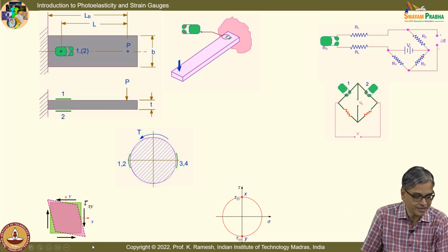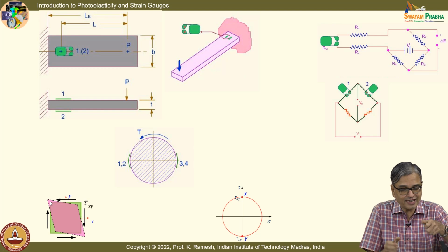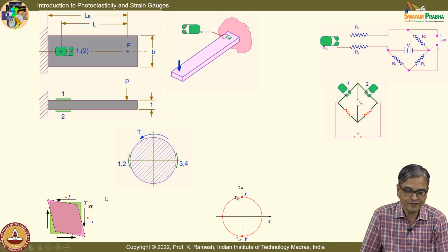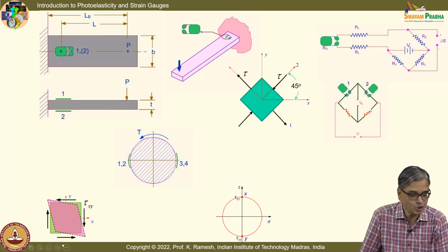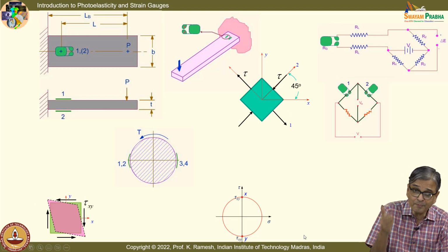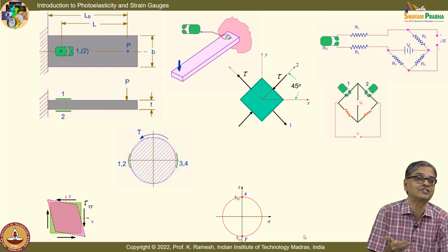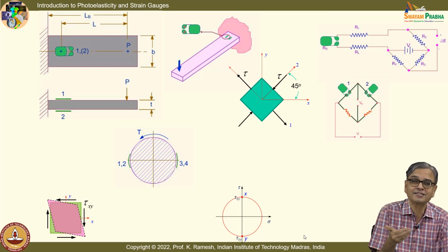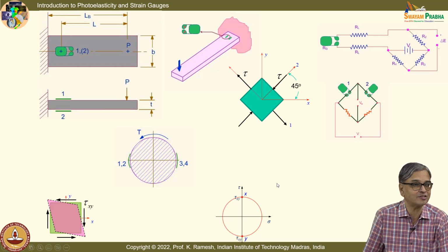So I have tension. So that is why your element is stretched like this and compressed the other way. And if you look at from a diagram like this, I can write an equivalent stress state in this fashion. Is the idea clear? That is important for you to recognize. How do I use my strain gauge to find out what happens when the object is undergoing a pure shear stress state? So it tells me that I have to align my strain gauge this way.